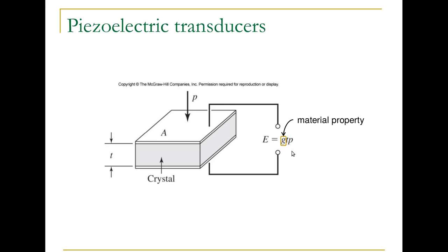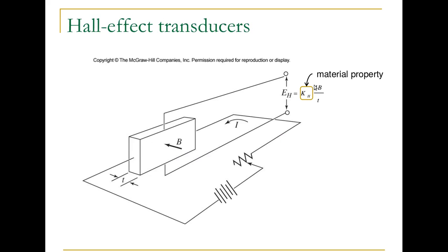Piezoelectric transducers are often used to measure pressure in high frequency applications. They're used as accelerometers, where we tie a mass of known value to the crystal and then measure the force required to accelerate it. And piezoelectric transducers can also be used as force sensors.